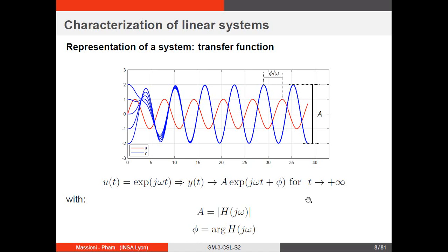This is very important to understand because it lets you see the transfer function as a directly useful tool. It's not something abstract, it's a tool which tells you that if you input your system with a sine wave at 10 Hz, you can immediately compute the amplitude of the output, still at 10 Hz.